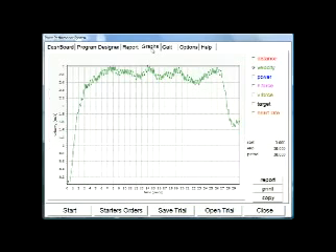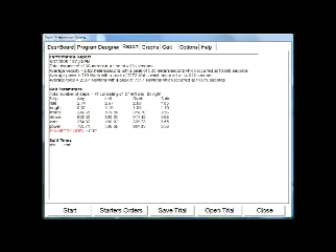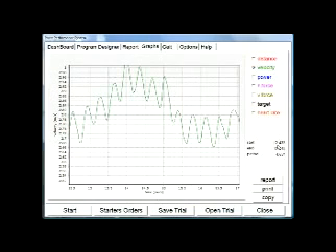We'll move back out to the graphs page, zoom into a portion of the graph, hit report. That'll change our report to just that period of the test. See, the total distance is only 13.06 meters now. The time is only 4.631 seconds.